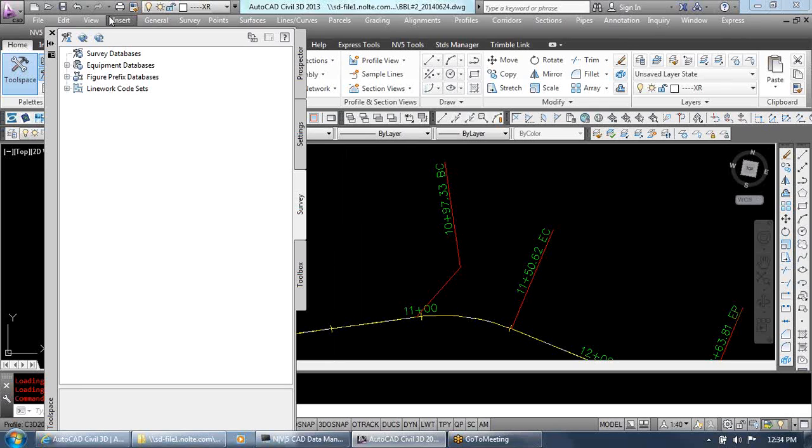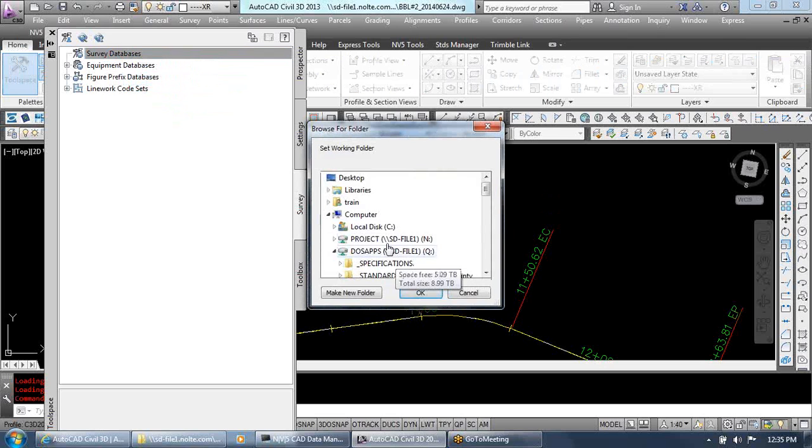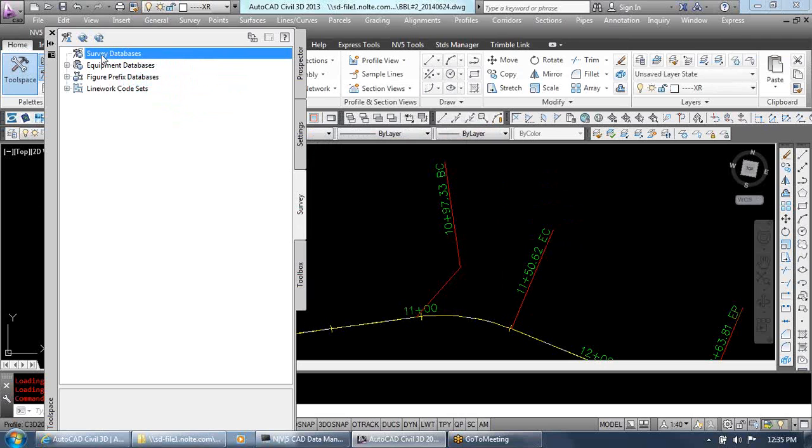I know one of the big issues with the databases is setting up the projection and the datums correctly, because you have to set it up in 2 different places, and if they don't match, your points start shifting by the international foot margin, which is somewhere around 12 to 13 feet. So you bring in points in one drawing, and then you bring them back out of the database into a different drawing, and all of a sudden your points are about 12 or 13 feet off. Because the default is set to international feet. So I think people have gotten used to setting the drawing settings themselves to US survey feet.